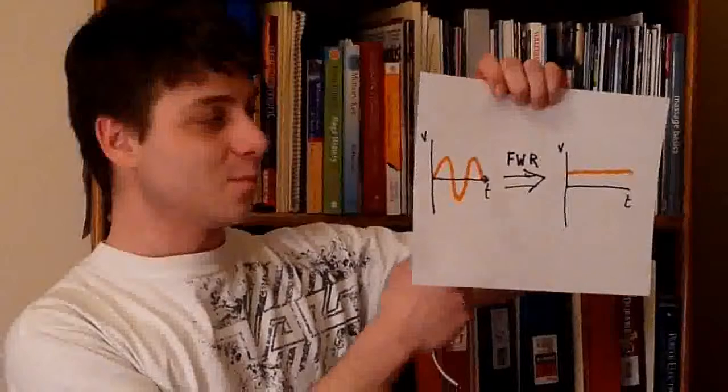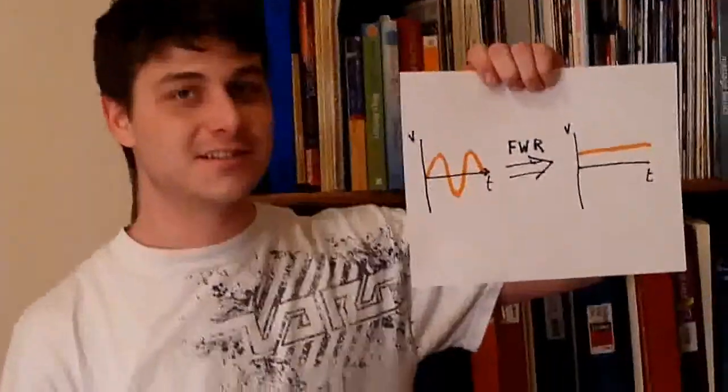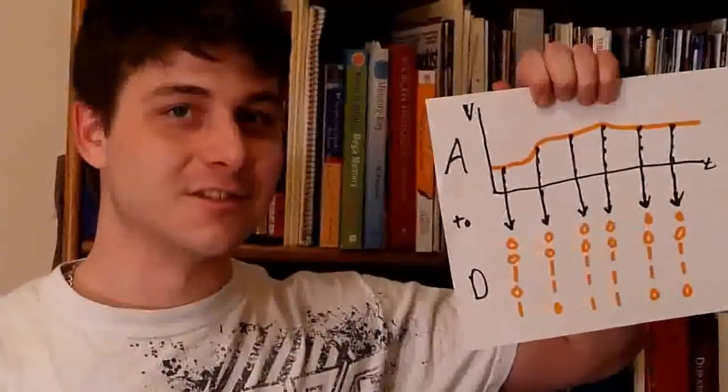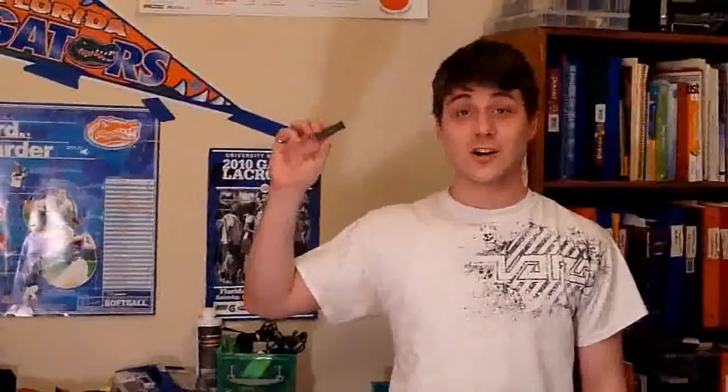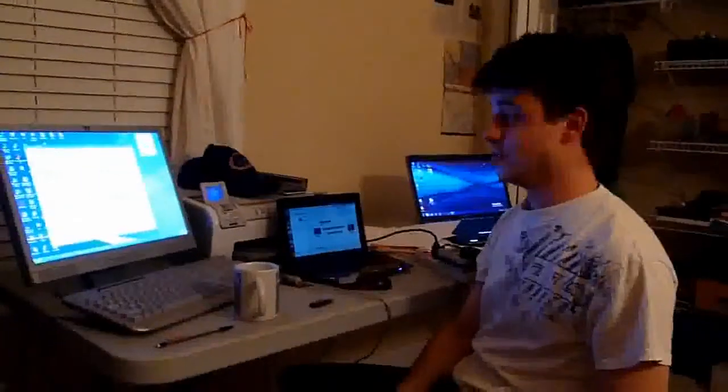The first step is to use a current transformer to get the induced voltage of the current we're trying to measure. Then we take that AC voltage and run it through a full wave rectifier to produce a DC voltage. The next step is to use a microcontroller with an analog to digital input so we can digitize our rectified measurement signal. The next step is to use the microcontroller's UART to send serial data to the PC. The last step is to write a GUI for the PC to do calculations and graph the data.